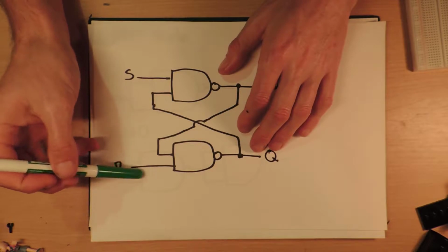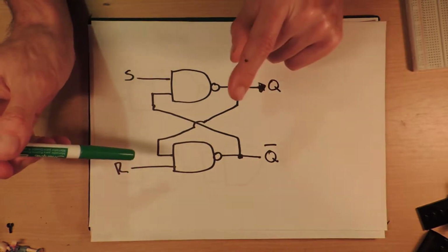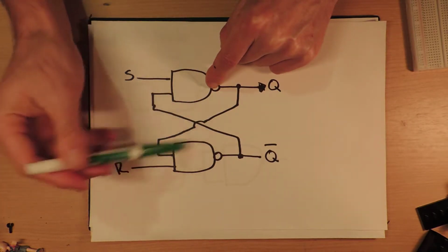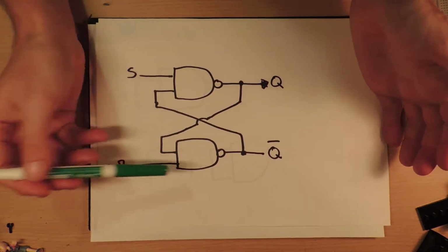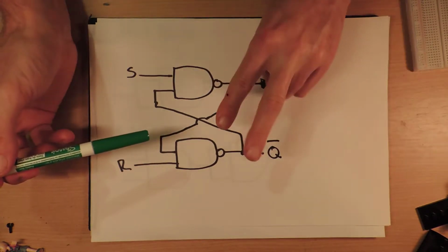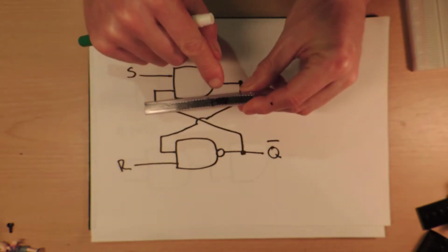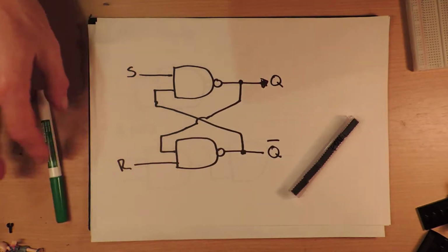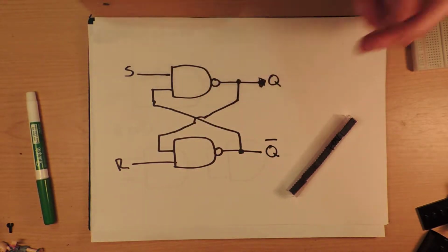And technically, I think if you're using inputs from other CMOS chips, you could get 3 reset-set latch things. I've got so many names for them. I keep calling them RS latches, so I will call them RS latches. You can make 3 of them out of a 4049, but you're only going to be able to get 2 of them out of a 4011 because the 4011 has 4. So it's a quad. I didn't mention this before. It's a quad NAND gate, so it has 4 of these little circuits inside of it.